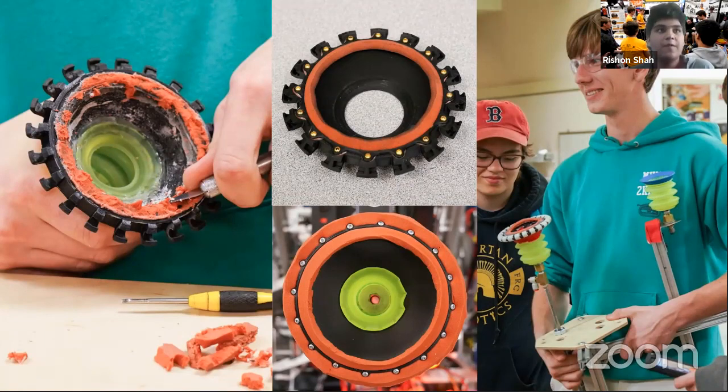So we ended up switching to attaching the foam by pinching it, by taking a 3D printed ring. You can see that in this picture right here. And this 3D printed ring had holes for screws, and those screws would go through the foam and into the 3D printed lip behind it, and that's how we secured the foam in a way that made the foam really easy to replace.